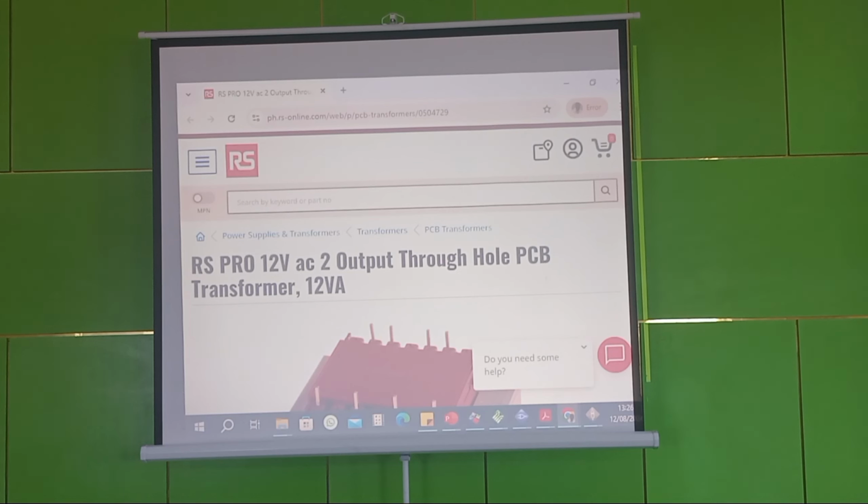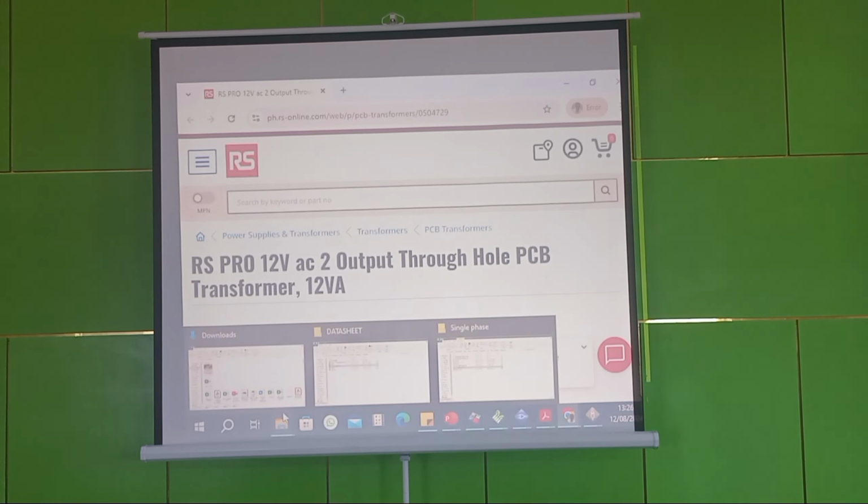Most of all these things we are going through, you have all this information in the data sheet. By the time you want to do any, you see it. Everything is already there. I'm just putting it through in case. Because if you have an existing component for which you don't have the data sheet, you have to create those patterns. If you don't create those patterns, there's no way the component will fit into the PCB board. And for every pattern, there's a name for the pattern.